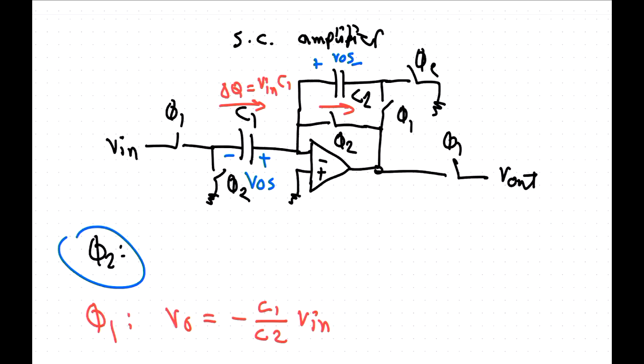You measure the phase difference at the input and digitize it directly, and then a digital control system drives a digital controlled oscillator. This is quite common, and it's happening more and more that you move stuff into the digital domain. Whatever wraps around it is still the same circuit work you have to do, but it becomes thinner and thinner.